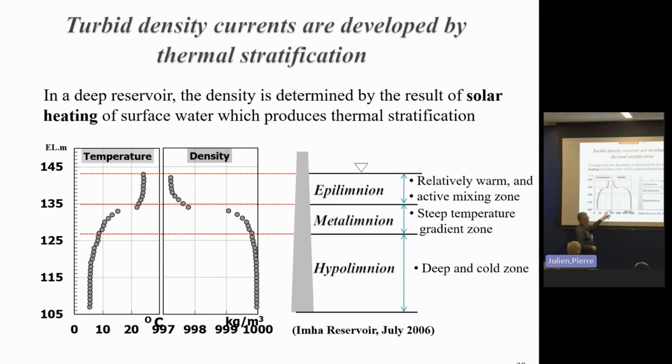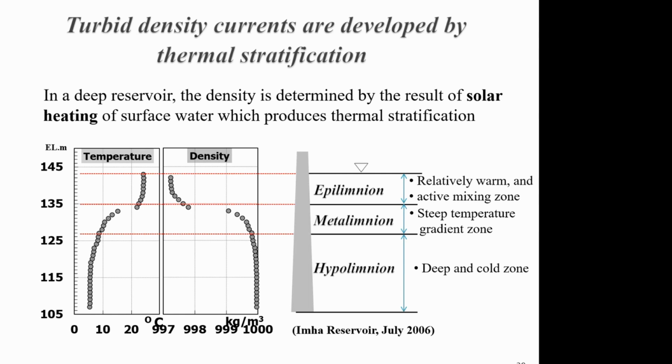You get the epilimnion that is going to have higher temperature, 20-some degrees, so depending on where you are, California versus North Dakota, you may have different values, but typically on the order of 20 to 25 degrees Celsius in the summer. And that can be about 10 meters, so that's 30 feet of depth there. Below that, you're going to get colder water down to 4 Celsius and maybe a little bit warmer, even in shallow reservoirs and whatnot.